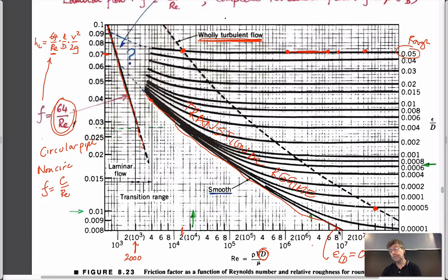In this particular case, the magnitude of the friction factor is changing all the time for this smooth pipe. And I guess the argument would be, if it's truly infinitely smooth, if that's a real term, if it has zero roughness, then it tries never to be able to set off turbulent flow because the flow regime is stable all the time. So what sets off turbulent flow is this little undulation on the bottom. It's a bit like the idea of the Tacoma Narrows Bridge.